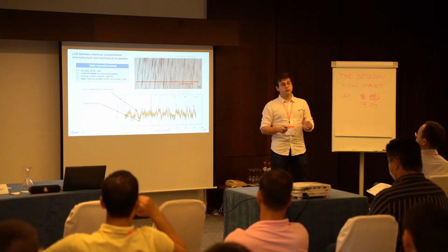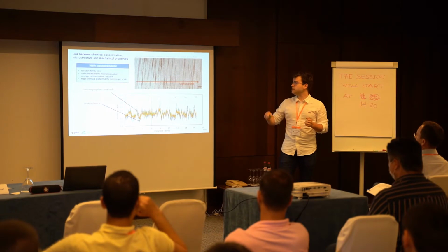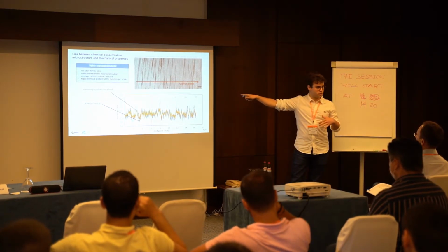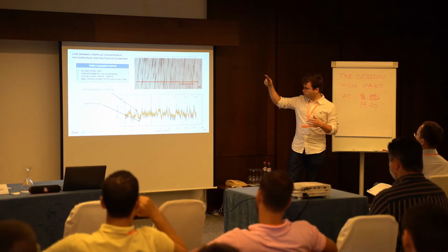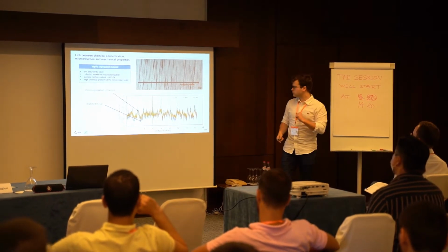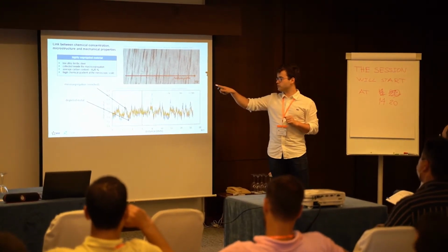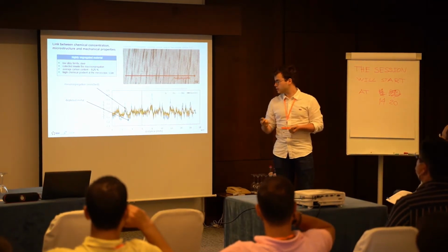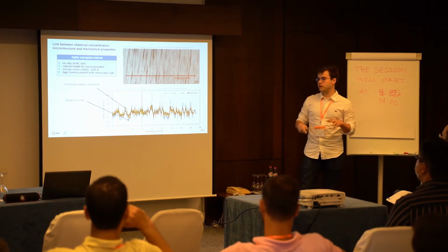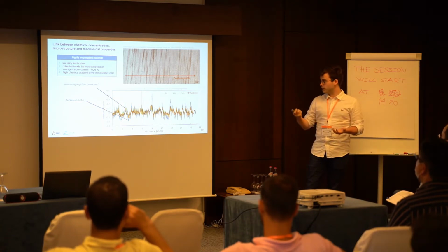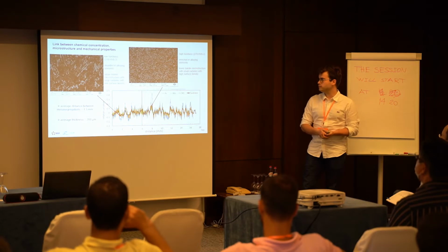Here you can see a chemical analysis performed on the highly segregated material along a line perpendicular to the meso-segregations. As you can see, there is fluctuation of the chemical alloy composition of the main elements between the meso-segregations that are enriched and the depleted metal. The black line here represents relative hardness variation and is very well correlated with the local chemistry because of the local microstructure that you can observe here.